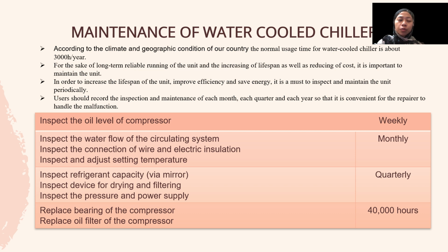First, inspect the water flow of the circulating system. Second, inspect the connection of wire and electric insulation. And last, inspect and adjust the setting temperature.